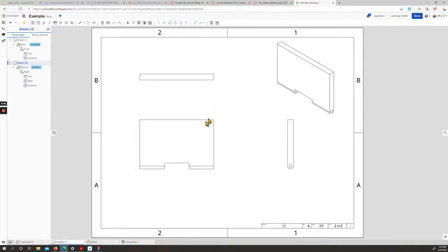Okay, I'm going to hit escape so it's off my key. I'm going to right click, show our shaded view. There we go. And again, do our general dimensions. Okay, we have our overall height. We have our width here. Sorry, length, width. So if you see something like this, it doesn't give you the whole height. Okay, what we'll do is we can choose the top and the bottom line, and that'll give us our entire height.